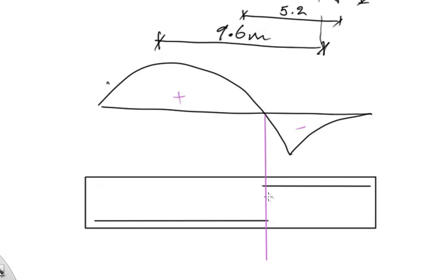So that's one of the reasons you need to know where the negative moment starts and where it ends, and the same thing goes for the positive moment. I mean, there are a lot of other reasons, but this is the most common reason, probably the very first reason people are gonna discuss if you ask this question.